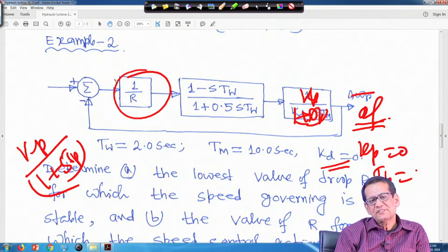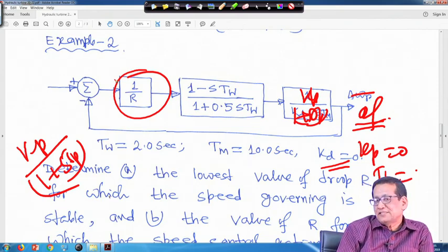That is why, when you take, from a theoretical exercise or for academic interest, the transfer function of the governor and see the responses, it takes more time to settle because of its time constant, right. It takes more time to settle compared to a steam turbine. And when you use an interconnected system, one area a thermal system and another area a hydro system, because of this effect you will find it takes longer time to settle, right. So, these are some general ideas.